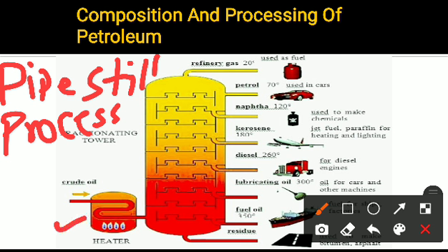In this tank the emulsion is allowed to settle, as a result of which the emulsion is broken into two separate layers. The oil is separated to the top layer, while the wet sand, that is the sand with the water, forms the lower layer. Both layers are separated and withdrawn.